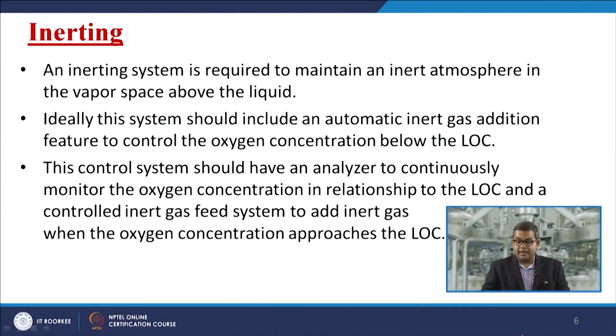Ideally this type of system should include an automatic inert gas addition feature to control the oxygen concentration below the limiting oxygen concentration. These control systems should have an analyzer to continuously monitor the oxygen concentration in relation to the LOC, and a controlled inert gas switch system to add inert gas when the oxygen concentration approaches the LOC.